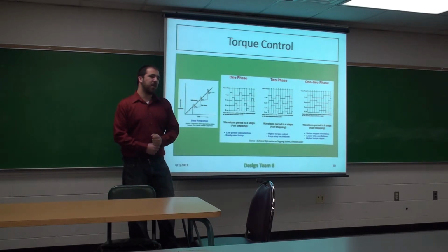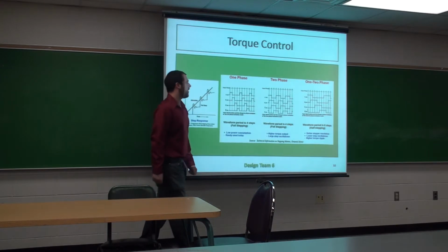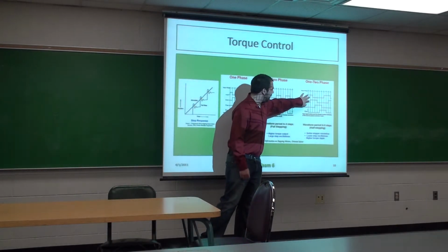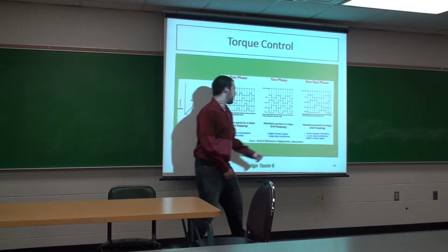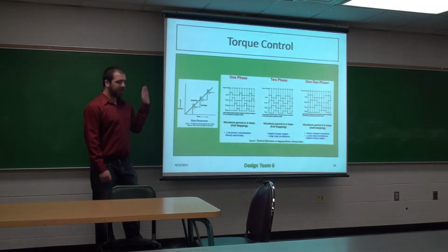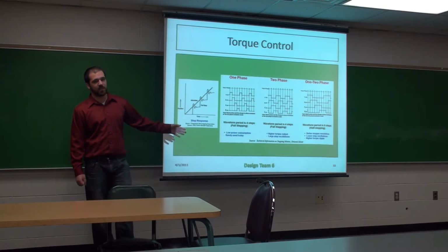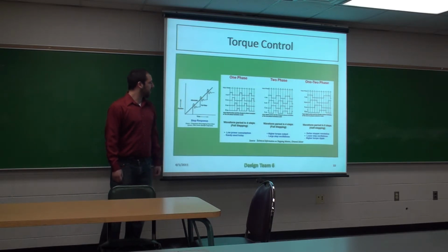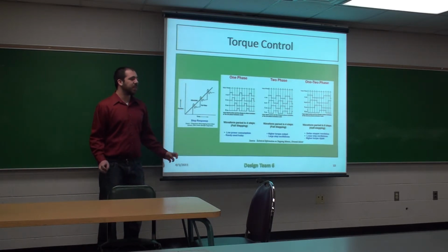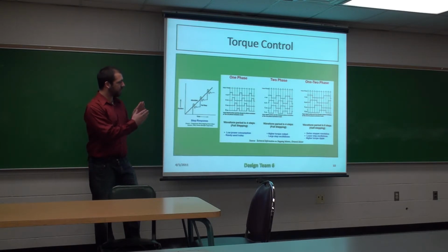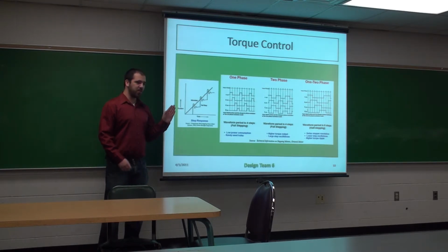What you can do to reduce power but still have high torque is you can alternate between having one phase on and two phases on. What this does is you get a better resolution because instead of going the full step, you stop halfway in between, so you have twice as many steps now. You can actually go all the way up to an infinite amount of steps if you use pulse width modulation, and you'll eventually go like 1/32 of the way and keep going.